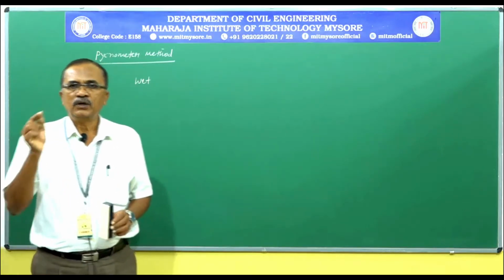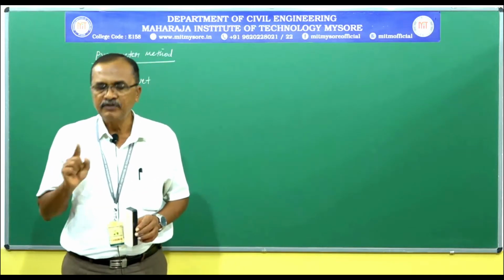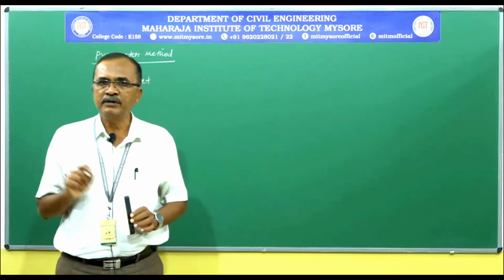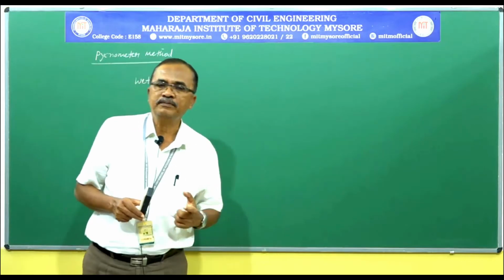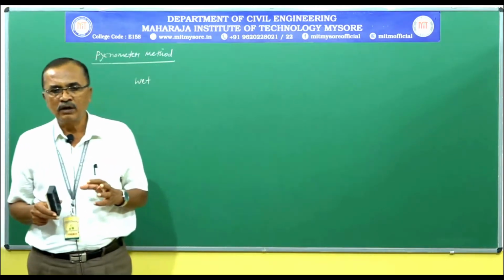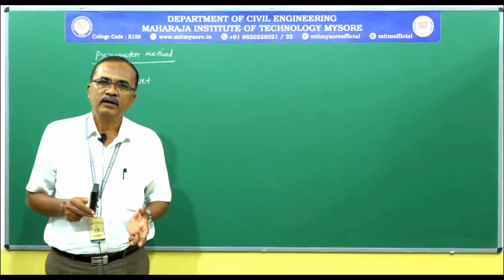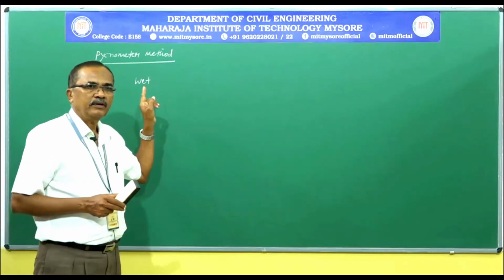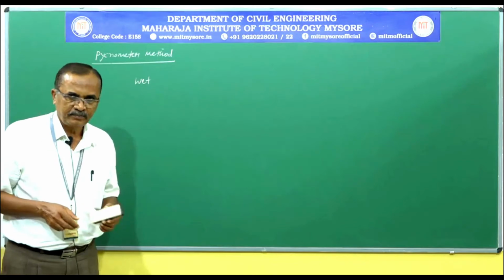In the Pycnometer method of determination of specific gravity, we use dry soil passing a 4.75 mm sieve, whereas to determine water content of the same soil, we use the wet soil as it is, and to determine water content we need the specific gravity.